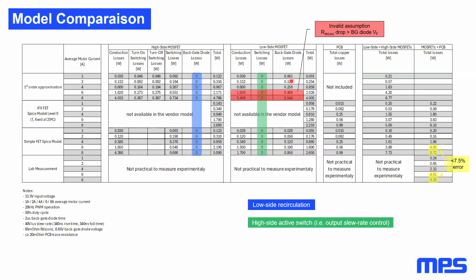To be noted that also copper has its own thermal effect, with an increase of resistance with increasing temperature. This effect is more complex to model, though, as one should be able to extract the thermal characteristics of the PCB. So we have left out this effect together with the reverse recovery of the body diode and other approximations mentioned so far.